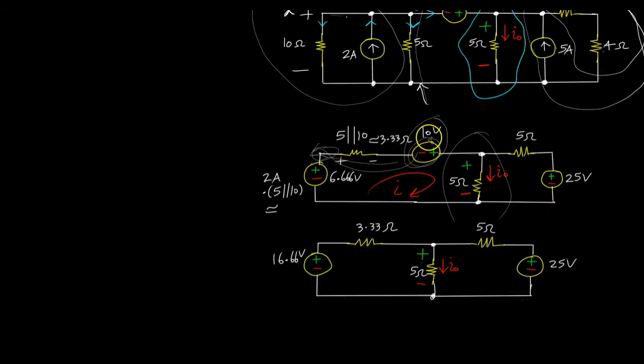Okay, so in this case I've gone ahead and moved the 10 volt source to the very left of the resistor. Then I've combined the voltages, because you can do that. If you recall the mesh equation again, you would see the negative 6.66 as you go up. Then you would see the moved voltage, which is negative 10. Now I can simply combine the two and get a negative 16.66 as I go up from the bottom. And so that's what I've done here. The math shows you that conservation of energy is still applied here, and it's not violated.